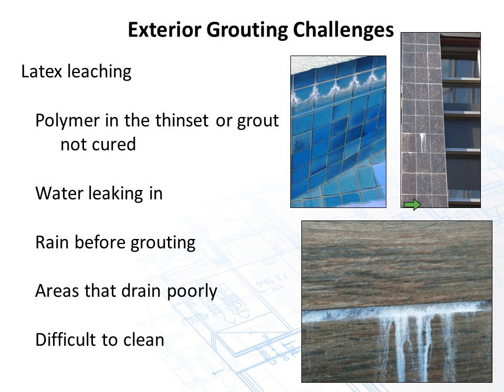Like I said, check for leaks. Make sure that there's coordination between the tile company and the construction company, that the roof material, if you might, gets over the top of it, that you've got drip edges where you have terminations. If they put signs in your wall, make sure that that's properly sealed before they start attaching the sign. At terminations with right returns, make sure there's a drip so you don't have it returning all the way underneath that right area or underneath the soffit for that matter. Any areas that drain poorly or if sealants aren't installed properly, you're going to have issues.